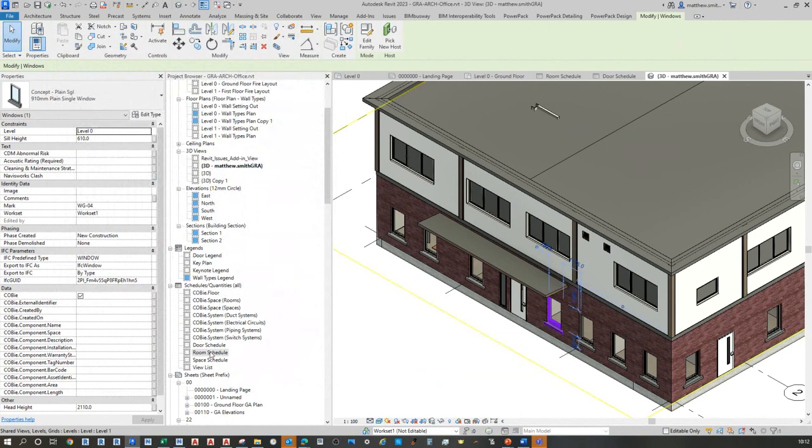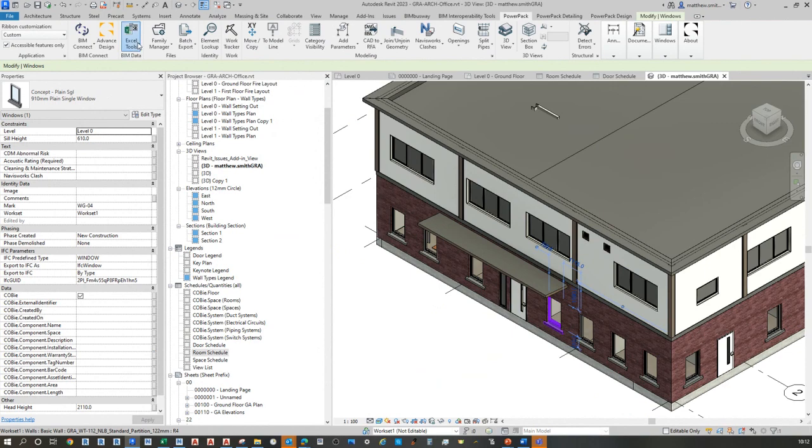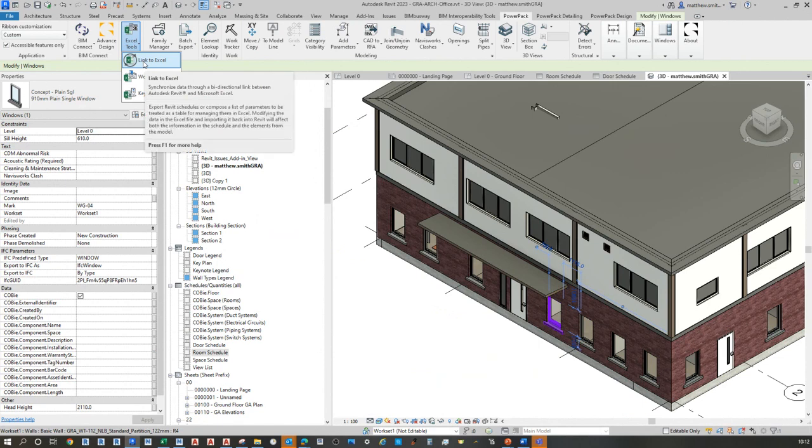We can export any schedules we create within Revit using Dynamo or a third-party product. In particular, the Greytech Power Pack gives us the ability to export schedules to an Excel file. This would then allow me to copy the data from that Excel into the asset register import.